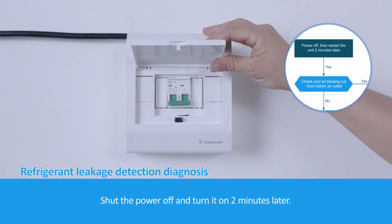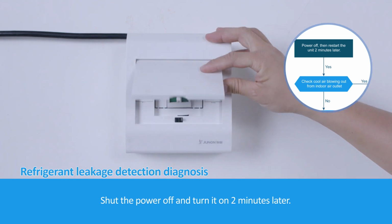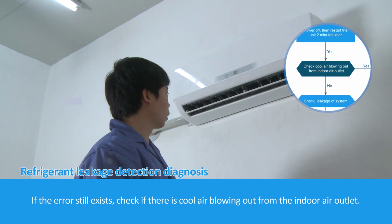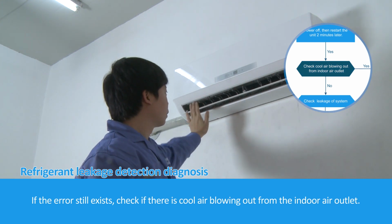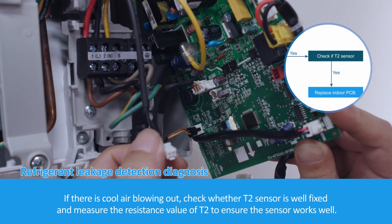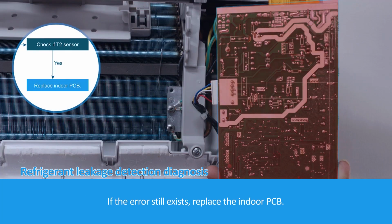Shut the power off and turn it on 2 minutes later. If the error still exists, check if there is cool air blowing out from the indoor air outlet. If there is cool air blowing out, check whether the T2 sensor is well fixed and measure the resistance value of T2 to ensure the sensor works well. If the error still exists, replace the indoor PCB.